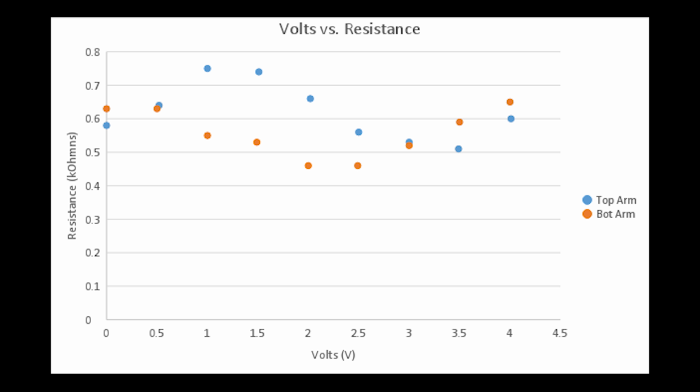As seen in our graph, this is not on-off modulation, given that this is pretty much impossible to get given our setup. Based on this plot, you can see that with 4 volts of movement of the PZT, we get a full period of change of one of the outputs. So ultimately, 2 volts of applied voltage to the PZT is equivalent to 150 nanometers of mirror movement.